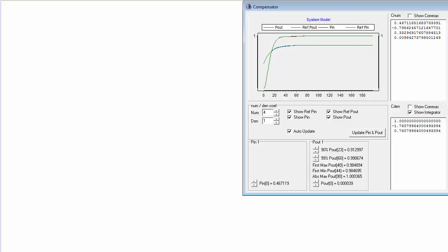After 4 numerator coefficients, adding more coefficients adds accuracy to the plant input and plant output. So let's increase this right on up to about 8 or 9. Now you may have noticed that as we pass through 3.1 and 4.1, those are both interesting possibilities. We'll come back to that later. Alright, so now looking here, we're at 9 and 1, and the numerical contribution of this ninth coefficient is relatively small. Let's dial it back to 8.